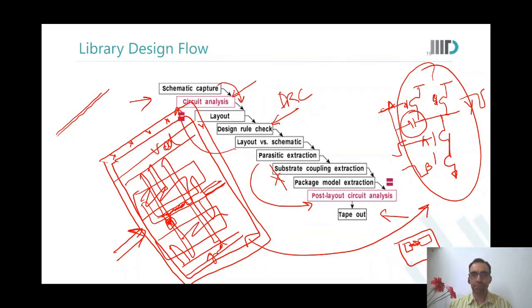But wasn't the problem that the current was flowing into the substrate? So if the guard ring is also a substrate... Yeah, but it is giving it a power supply, no? The guard ring is fully connected to VDDS or GNDS or whatever is the substrate supply. Very richly connected. So no noise from the analog circuit can go to the digital side, nor from the digital circuit come to the analog side, because there is such a huge sink, such good connectivity to substrate power in this guard ring.